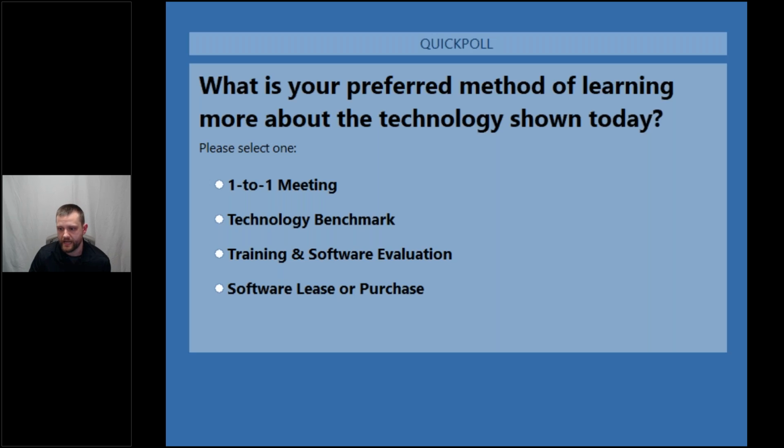So it looks like I have here: does STAR-CCM+ version 24.02 support radial turbomachinery blades? You can do radial turbomachinery blades in STAR-CCM+. We don't have the fully automated turbomachinery mesher available for radial turbomachinery blades, but we can use other meshing algorithms to evaluate radial turbomachinery, and we have customers that do that.